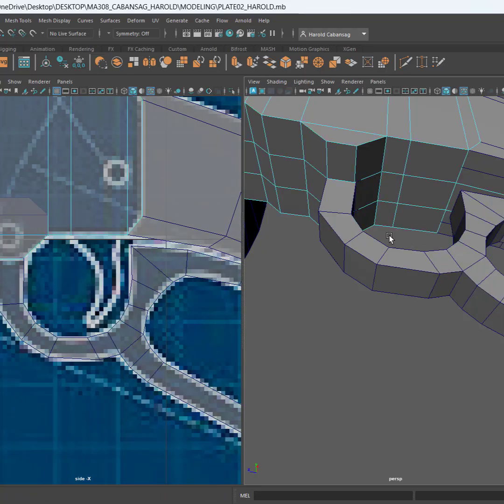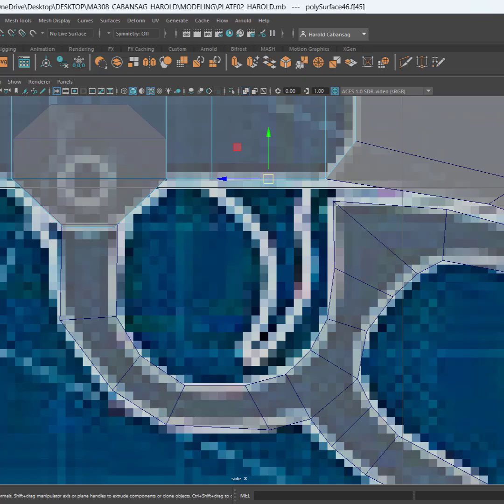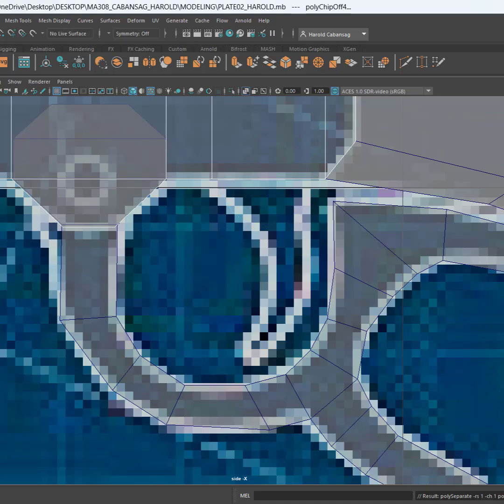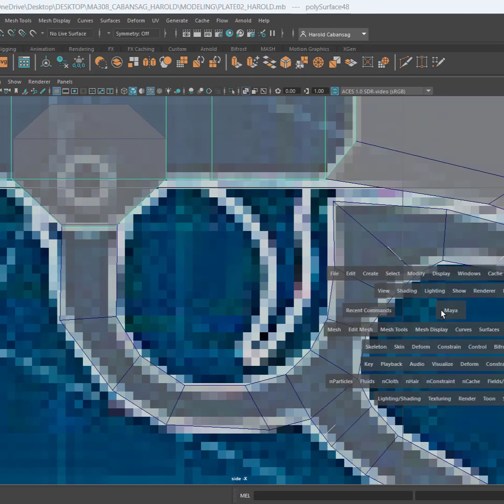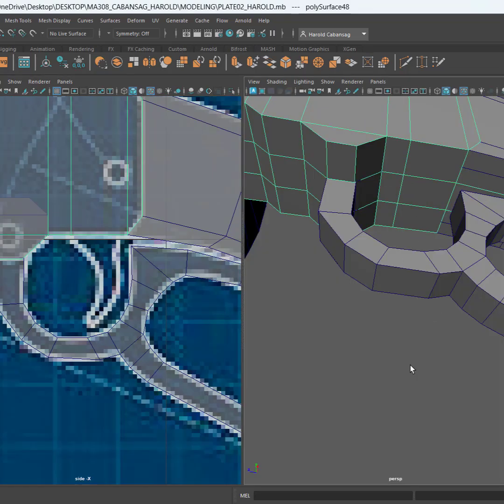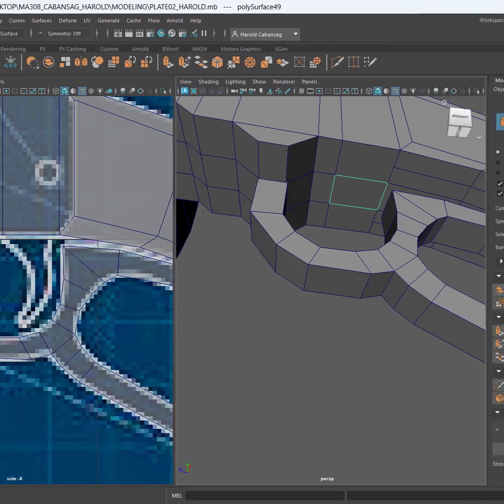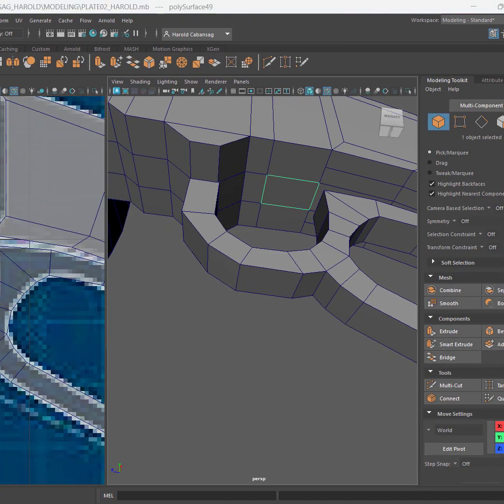Next thing, I can also get from this object for the trigger. I'll just select this, and then again, once more, edit mesh, duplicate that selected object, and then I can select it there, here, W, go to tools and reset so that it's at the center once more. There it is.